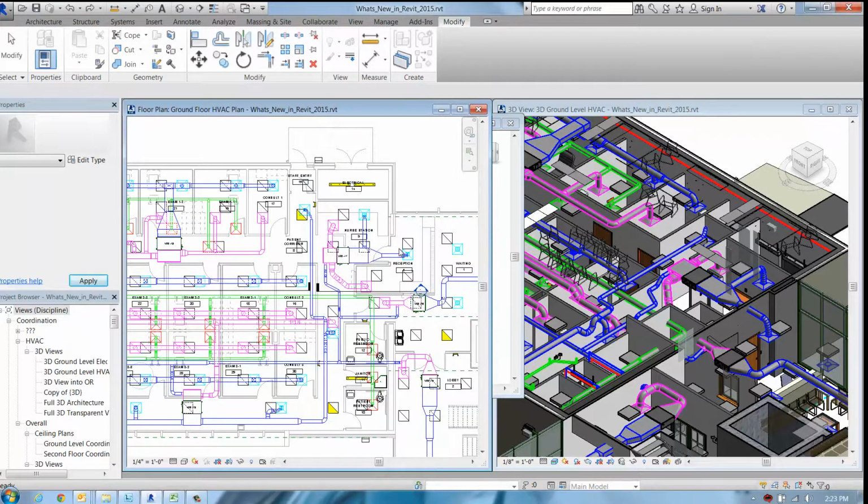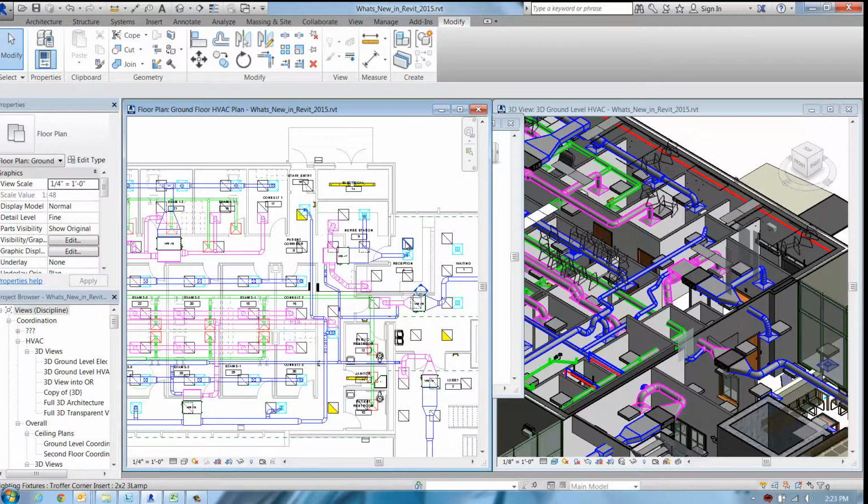Load it back into the project, and then you change out the parameters, then you'll see those things reflected when you pick on a particular instance of that family.